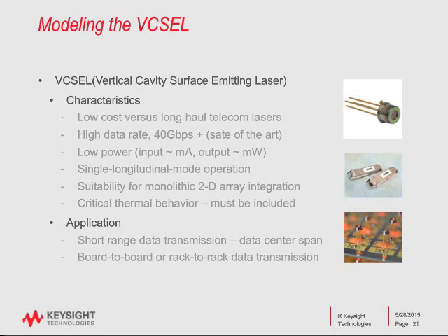So modeling a VCSEL is not a trivial thing to do. It has characteristics that we're all pretty much aware of. It's short haul for the most part. It can support high data rate, so the model has to be able to deal with that. We're working with low powers, typically milliamps, milliwatts.